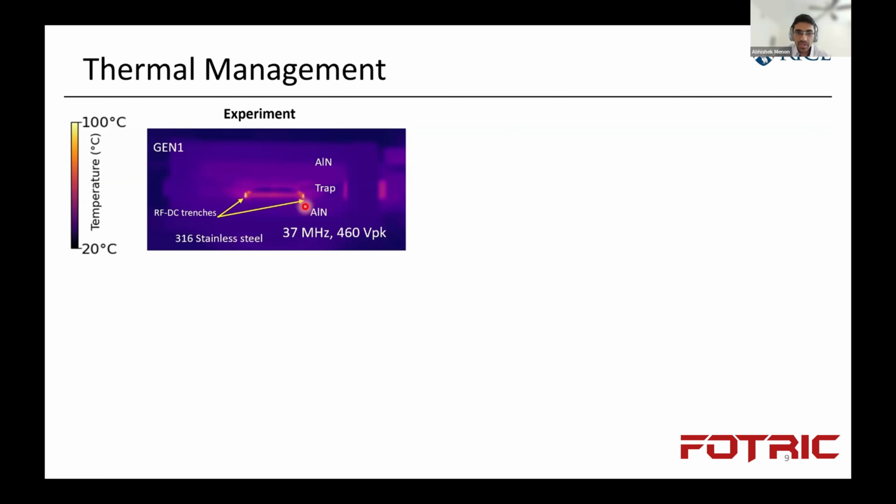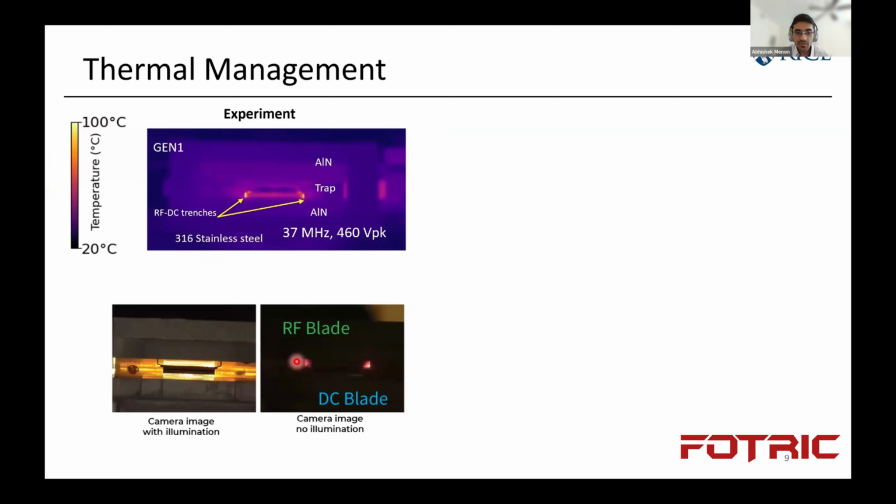And if there was maybe one particular hotspot that was much, much more than the other, and it was less than 100 microns, we wouldn't have been able to resolve it as much, and it could have been averaged out. So for that reason, we were not able to very accurately determine what the temperature was at those spots. And that's also part of the reason why we were seeing discrepancies in the air imaging temperature and the visible temperature, particularly for the Gen 1 version of the trap.